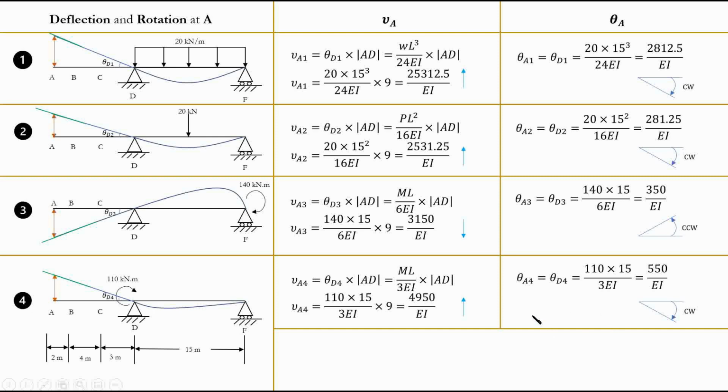Now, the question might be, is this enough? So is that it, as we did for point E for the deflection in the midpoint? And the answer is no. We have a cantilever portion, as we discussed before. We have direct loading, 2 additional cases for the cantilever portion. Why? Because we're finding it at point A. So we found the effect of the simply supported portion, the adjacent portion, but the portion AD itself is remaining. So we have to account for that effect as well.